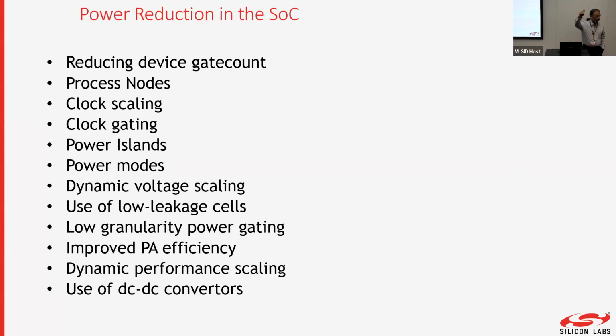The closer it goes to VDD, the more nonlinear it becomes. So to make it work only in the linear region, you have to bias the signal so that it only works in that area. That means even though the voltage is very high, you're never hitting it, so you're consuming a lot of unnecessary current just to keep your amplifier very linear.